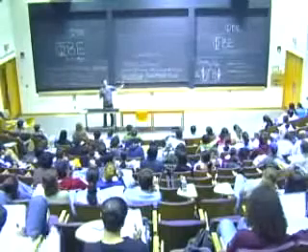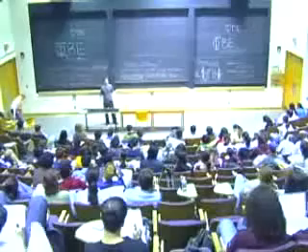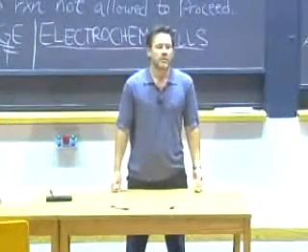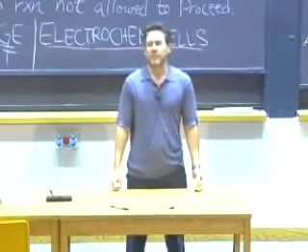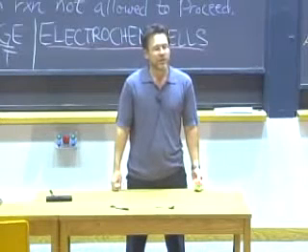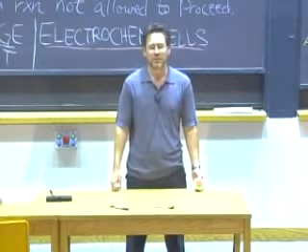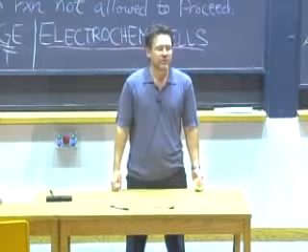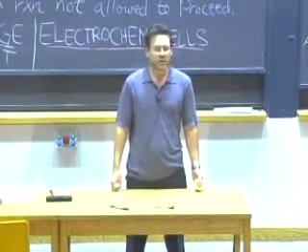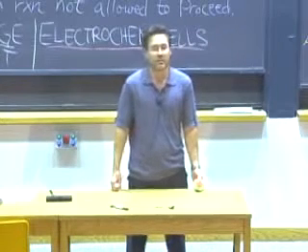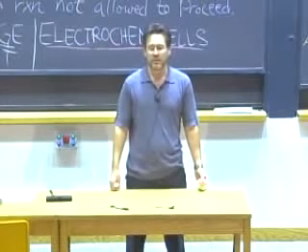And in setting that up and thinking about what's happening there in terms of depletion of one electrode so that the other one can be increased in mass, you may be aware of places where this principle is actually used in construction, for example. There are large steel bridges that are constructed, and one doesn't want those to oxidize away and become fragile in their structure so that the bridges break down and are not safe anymore, shall we say. And so what's often done there is large pieces of zinc are put into electrical contact with the metal of the bridge so that it's the zinc that gets oxidized away as a sacrificial anode instead of the bridge itself. The same goes for any of you who are sailors or boaters in general.